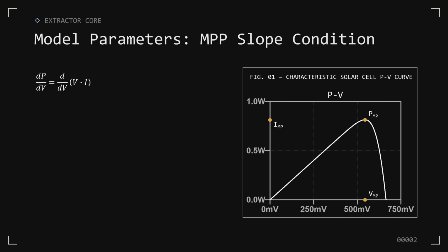So here's the form that the quick derivation just led us to. But since we already have di over dv from the previous condition, from the maximum power point, let's take the reciprocal and move the negative sign over to the other side to isolate RSH. Once you plug it in, the negative sign even conveniently goes away. Last time we evaluated this at the max power point, but this time we're looking at the short circuit point, so that's what gets plugged in for I and V. So the voltage goes away because it's 0, and I becomes ISC.